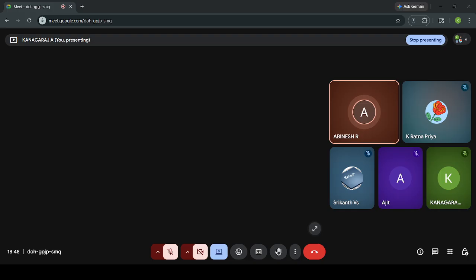Guys, you can see the FPGA here. Ball grid array, where the pins look like balls at the bottom. It is the bottom side of the chip. It is placed on the opposite side of the board. Opposite means you flip the chip and place the balls on the pads of the PCB.